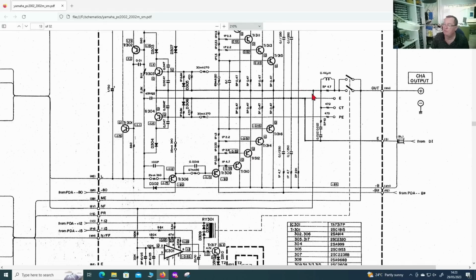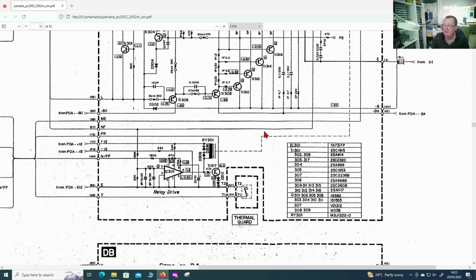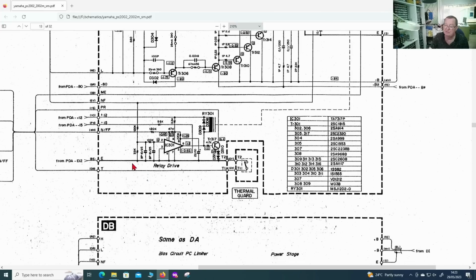So we monitor the voltage here, this side of the relay, and you can see the signal comes down here, along here, and through these 2 resistors. This end of the resistor network is ground. If you look, we have 120k from the signal, the audio waveform, and any DC offset, 120k into this IC, and we have 33k to ground.